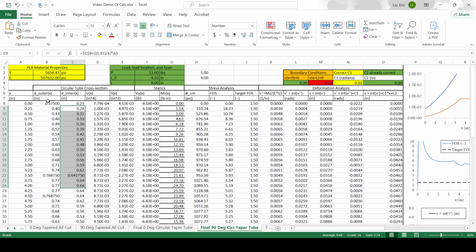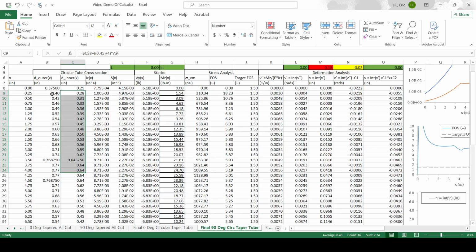radius diameter. Since we had to create some tapering increase to a flat line to decrease, what we ended up doing is we had a linear increase slope of 0.45 divided by 4. The 4 came from the halfway point of the beam, and then 0.45 just comes from a random variable we chose, and then we changed that various times to see if it would be better for our beam.